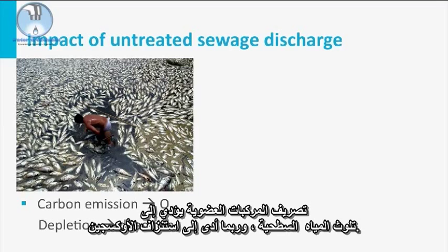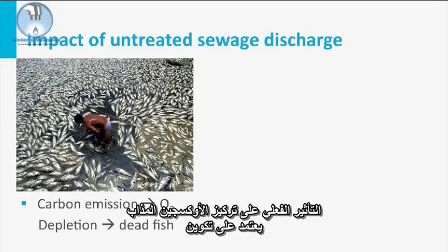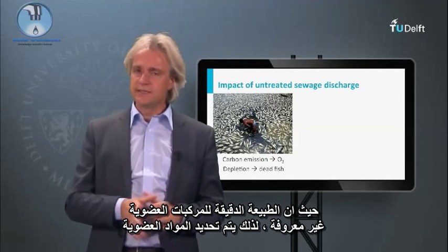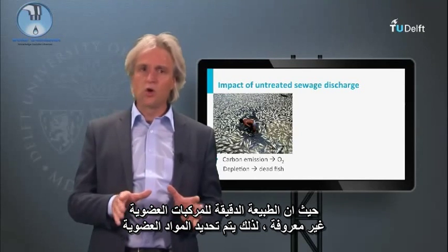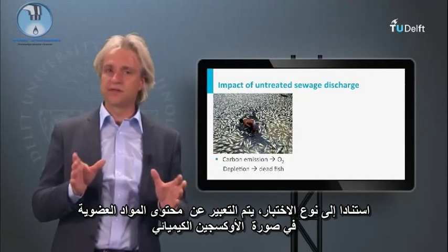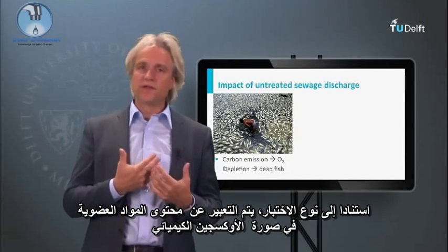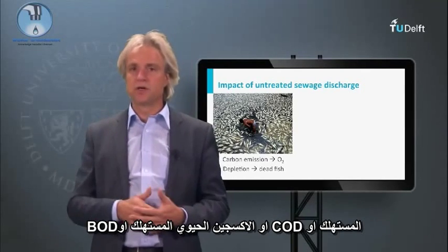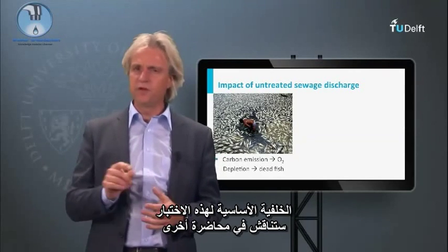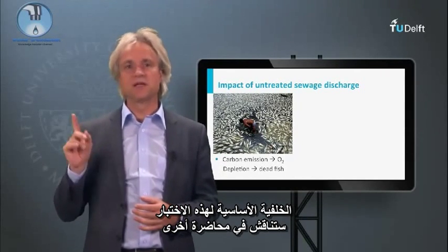Discharge of organic compounds leads to surface water pollution, possibly resulting in oxygen depletion. The actual impact on the dissolved oxygen concentration depends on the composition and concentration of the specific compounds, as will be discussed during the coming lectures. Since the exact nature of the organic compounds is not known, organic matter is determined in analytical tests. Based on the type of test, the organic matter content is expressed in gram chemical oxygen demand, or COD, or gram biochemical oxygen demand, or BOD. The fundamental background of these tests will be discussed in another lecture.